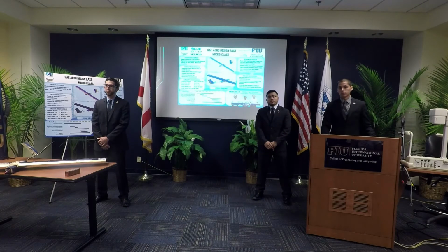I would look into that today. We tested going with a trimmed aircraft before you add the weight. You don't want to have that situation where you launch it and then your aircraft just stalls and you lose all your time in this project. So today make the adjustments to make sure that you can achieve a trimmed flight with minimal impact from your pilot.